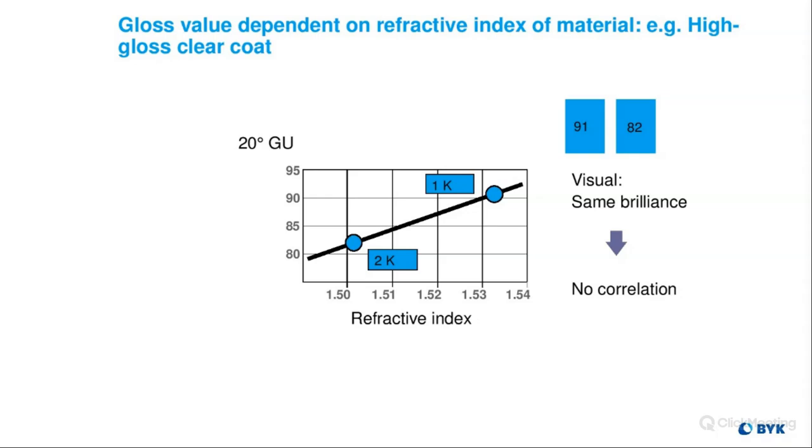Continuing on here. When measuring gloss on plastic, does the temperature of the sample play a role in repeatability? Yes. So again, just like the question that came earlier, the temperature doesn't necessarily play a role in the gloss, but it'll play a role in the instrument's ability to measure.